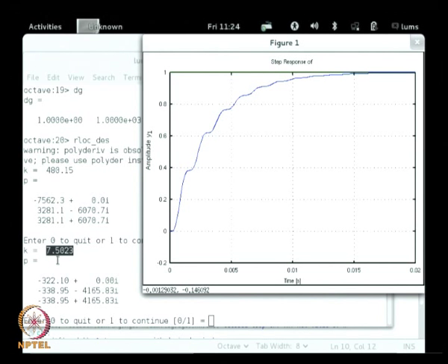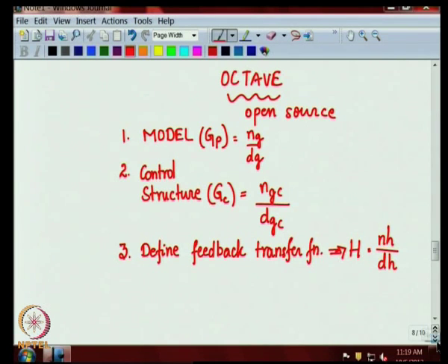You can now add, as homework, to this. We had right now given 1 by s. You can now make it s plus a by s, which means now you have put proportional plus integrator, which is 1 plus a by s.